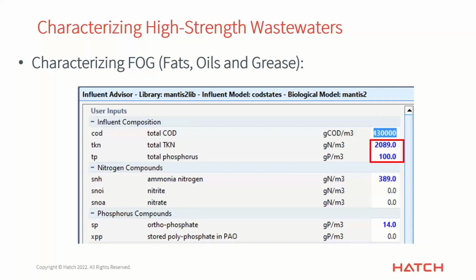But you're going to be looking at a very much larger value, sort of a typical ratio of bringing up the ammonia and phosphorus and soluble phosphorus up to a number that is in the same kind of ratio that you would have for your other waste. Now, what those COD to nutrient ratios are like is really dependent on the food waste itself. So for FOG, basically these kinds of numbers are something that will get you into the right neighborhood.